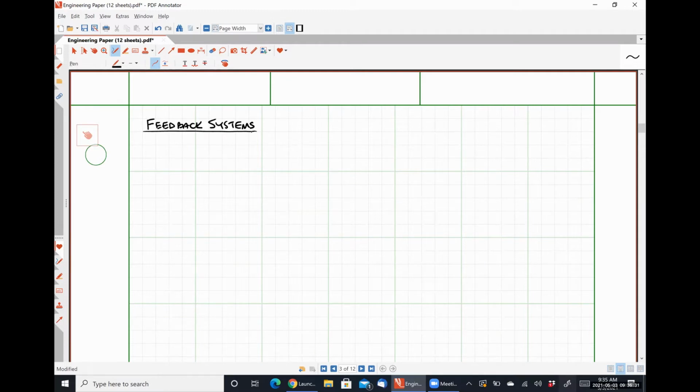Stabilize the output. That is a very, very good one. So specifically, I might be putting words into your mouth here, but the open loop gain of an amplifier is dependent largely on the process and things like that. So that means that if there's any process variations like resistor mismatching and all that kind of good stuff internal to the IC, we could see that the open loop gain does not behave as we would expect.